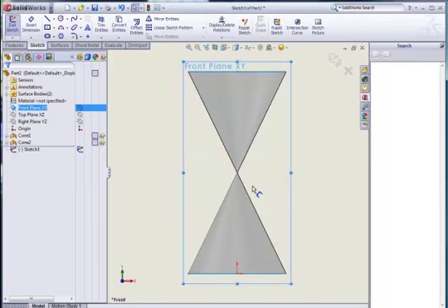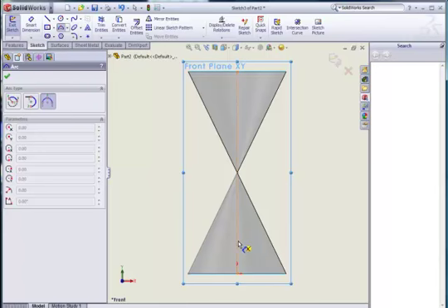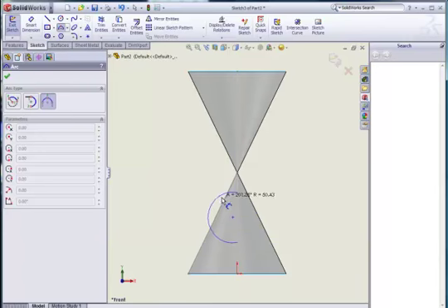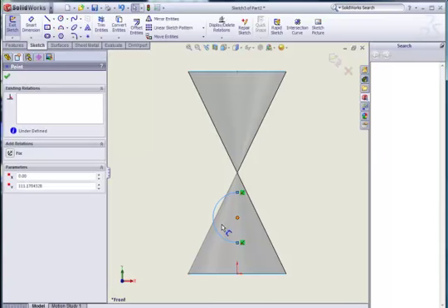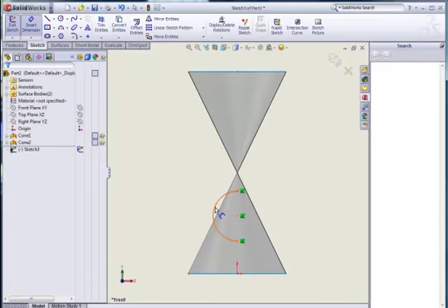and we're going to draw the first of our focal spheres by using the 3-point arc and then revolving it again around our center line. So draw the 3-point arc, draw the first point of the arc coincident with the center line and the second also coincident, and we add the radius. Now this is still undefined, but it is all coincident with our center line. So if we add the radius, in this case 45 millimeters,